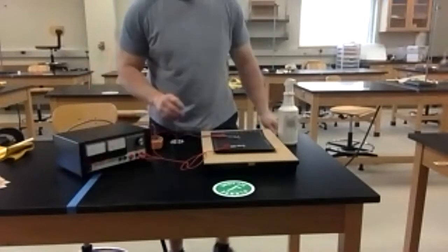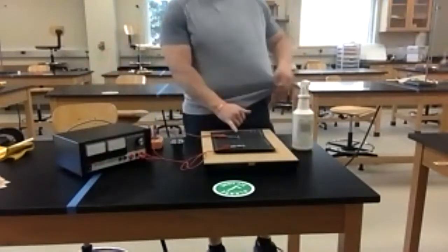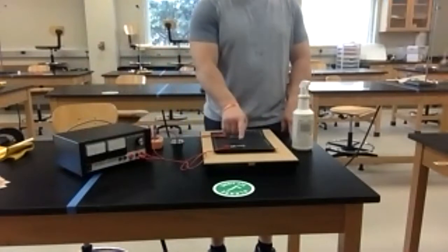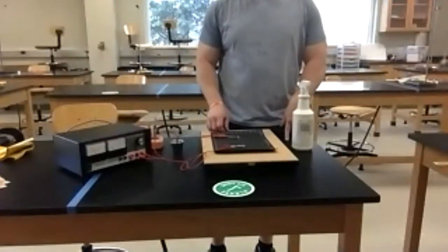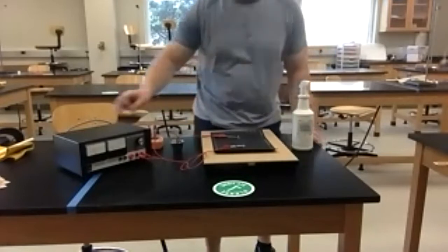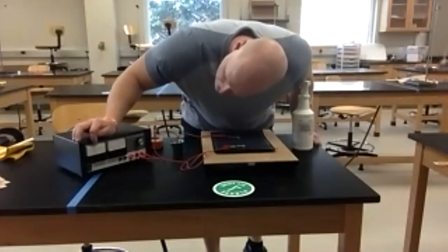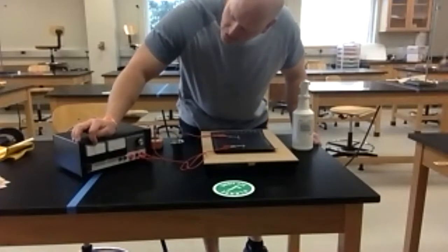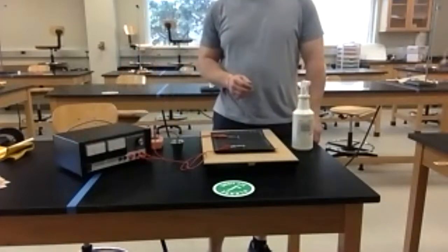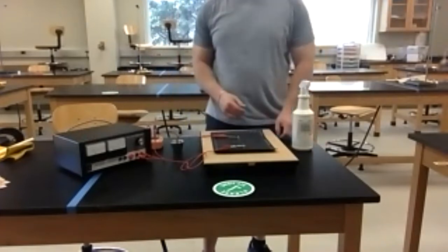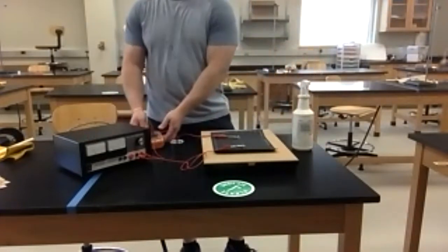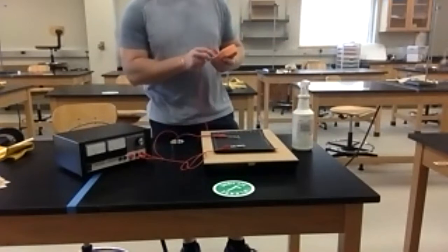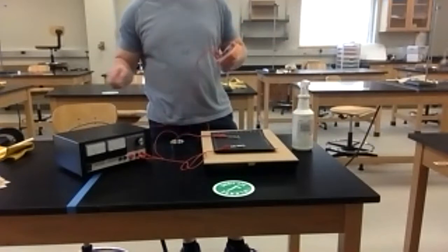And what that's going to do is it's going to set up a potential difference. So the negative terminal, it's going to set this guy equal to 0. This side, it's then going to equal to whatever it is that I set this thing at. So this thing is roughly set at, looks like a little bit below 6 volts, so maybe around 5 volts or so. So there should be about a 5 volt potential difference across here, but we're going to use our multimeter here or a voltmeter to measure that.